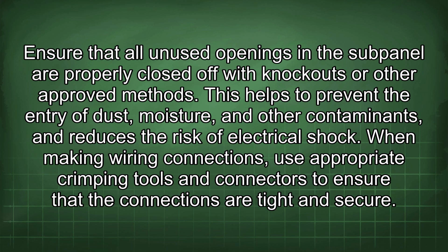Ensure that all unused openings in the subpanel are properly closed off with knockouts or other approved methods. This helps to prevent the entry of dust, moisture, and other contaminants, and reduces the risk of electrical shock.